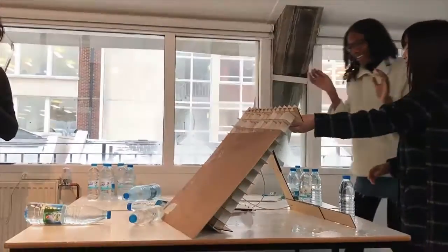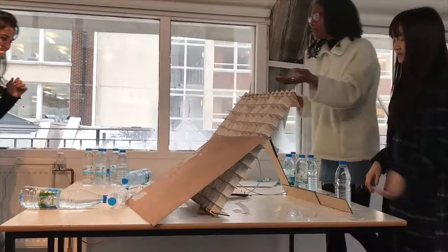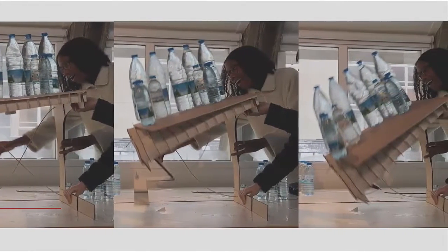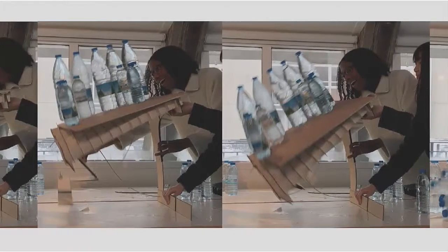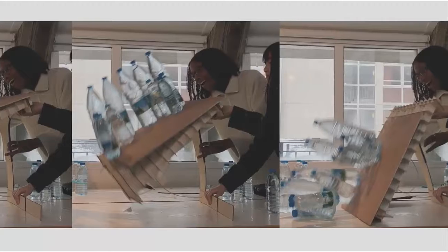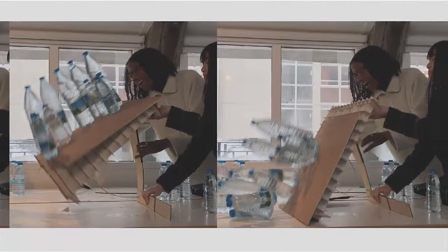On the smaller models, the legs in MDF were shorter, so they performed better when carrying the weight. As a conclusion, the legs were buckling because of the weakness of the material. Also, it failed because the force created compression on the legs, so bending happened, which caused the model to break.